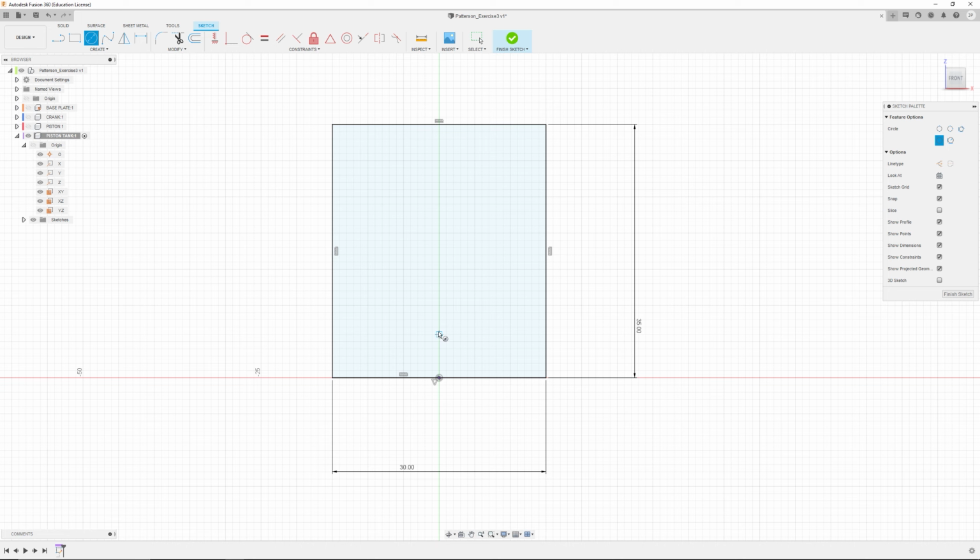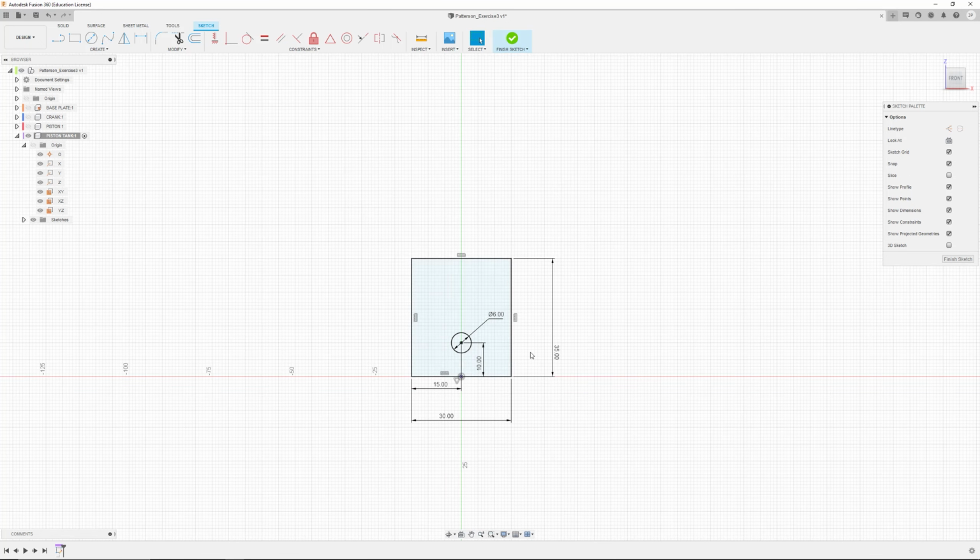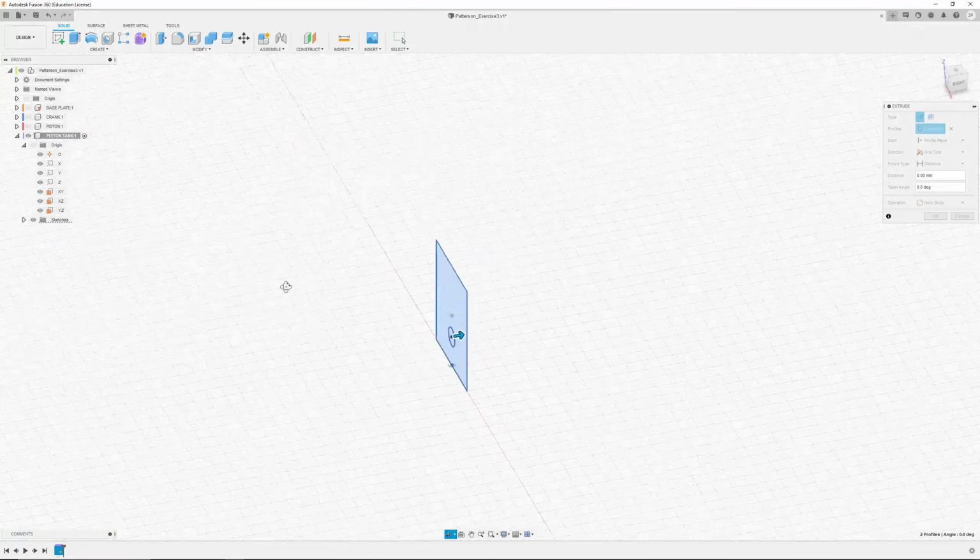And then this is going to have a pin in it. It's basically a mini version of our base plate. A diameter of 6, located 10, and it puts the dimension as 15 here, but that's just because I've already got it referenced as so. I guess we can leave it like that. Basically, I could have made that vertical as well. Either way would have worked. And then we're going to take this and that profile there and extrude them.